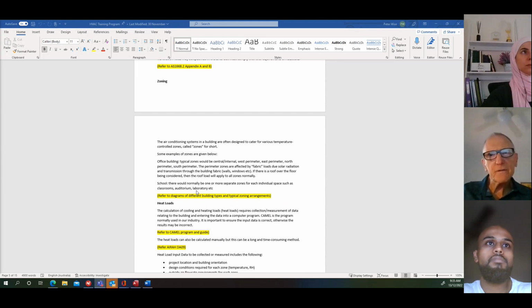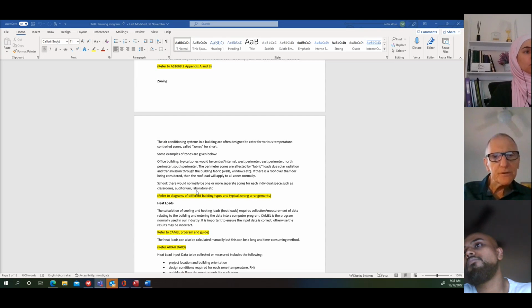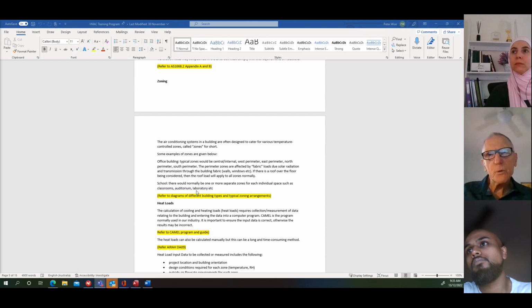That needs to be treated carefully because sometimes you just make that a separate zone, depending on the size of it. And Dua and I had one we talked about last week where, let's say, it was a northwest corner. I'm not sure that was what it was, but if it was a northwest corner, if it's not a very large space, you're better off to treat that with a separate unit, because otherwise you have conflicting zones requiring different temperature responses.